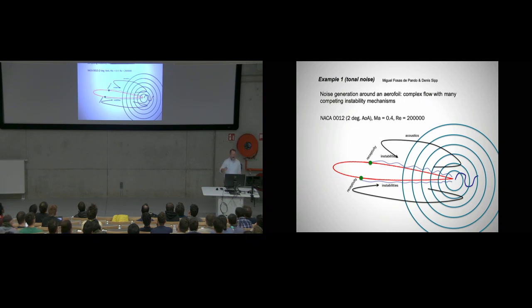Analyzing that one by doing local analysis, which has been done and published, by slicing the boundary layer here and doing a modal analysis with eigenvalues of the boundary layer, doesn't really capture anything that is essential for this type of mechanism.